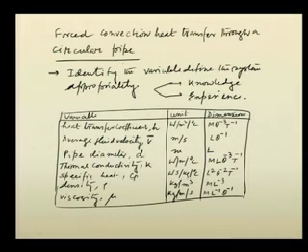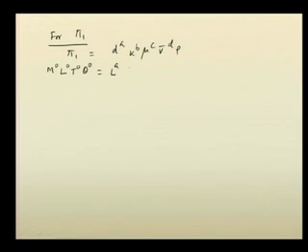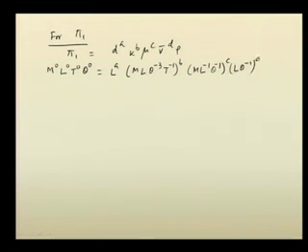So, we have to make use of the last column of this table. Then what we will write is L to the power a, m L theta to the power minus 3, T to the power minus 1 to the power b, then m L to the power minus 1, theta to the power minus 1, this is that for mu, whole to the power c, and then L theta to the power minus 1 to the power d, this is for v bar, average velocity, and then rho is m L to the power minus 3. Okay. So, this happens to be the case.